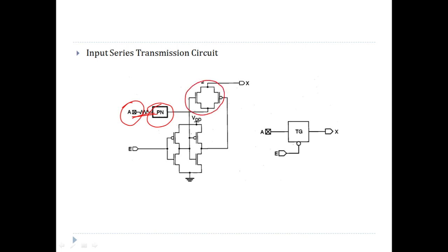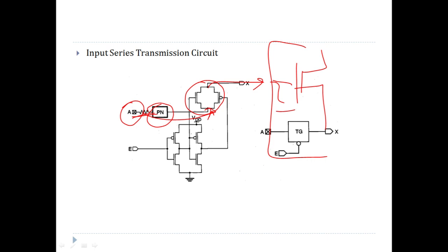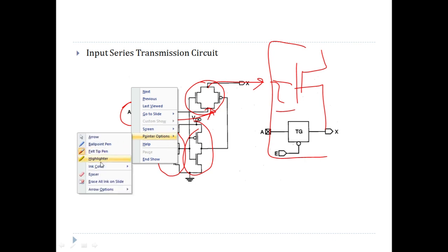Here there is a transmission gate. At the input of the transmission gate, there is an input signal, or the output of the protection network goes to the input of the transmission gate, and the output of the transmission gate is connected to the digital logic, where the logic is built and the input is applied to the logic gates. Now the controlling input or the strobe is controlled by cascaded inverters over here. You can see there are two cascaded inverters and they control the enable signal.